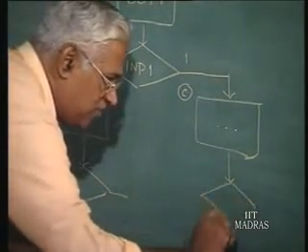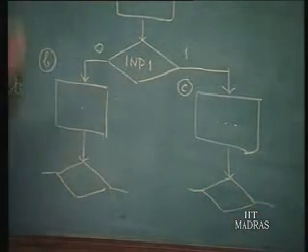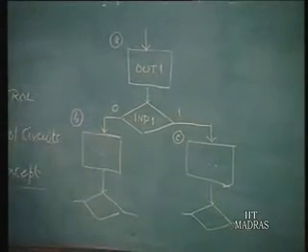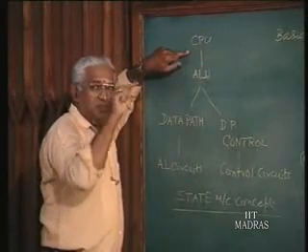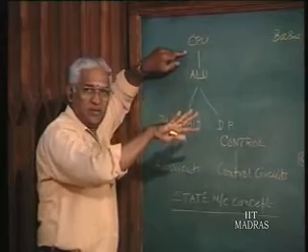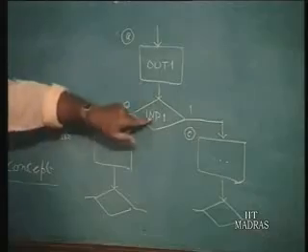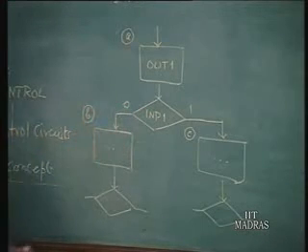Now this is a simple picture of a state machine. So this is precisely what the processor is doing. The processor enters, during the instruction cycle, one state. In that particular state it generates some signal, and it also looks for some input signal, and then it decides on the next state.